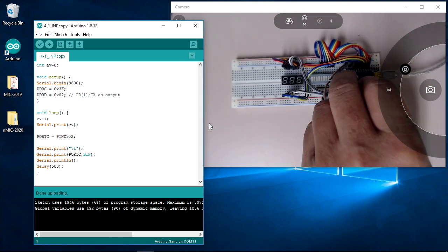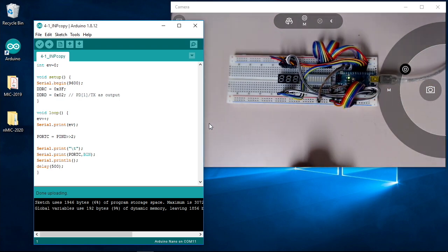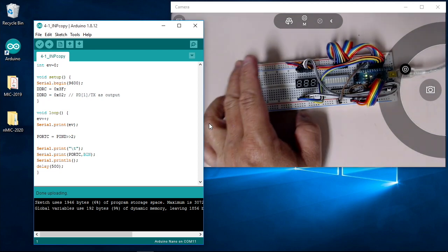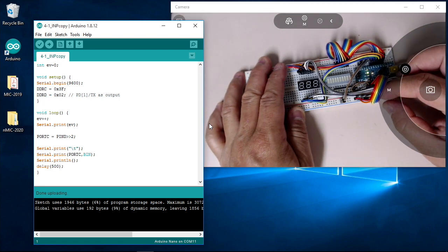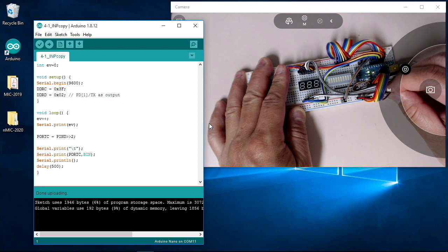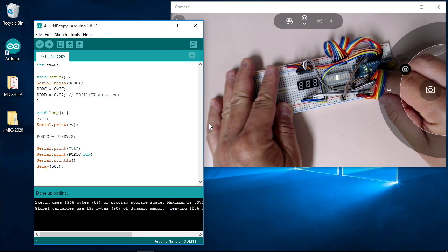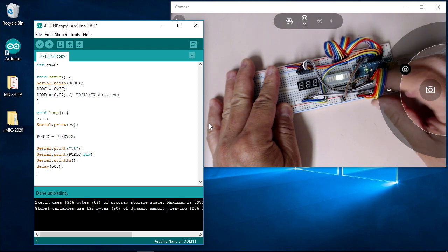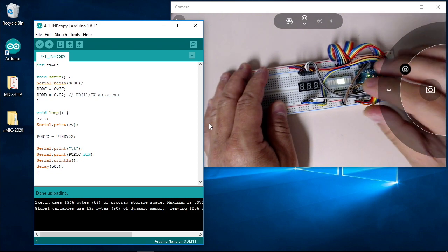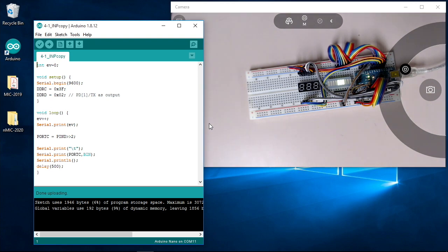So when I touch them now, no change, because the I/O pins are already defined by the electrical connection. So I put one to ground, or these 3 to VCC. That you can see, these 3 are now in a set state. So if you use an I/O as an input, you must well define the logic state by connecting the actual circuit. You can't leave it floating.